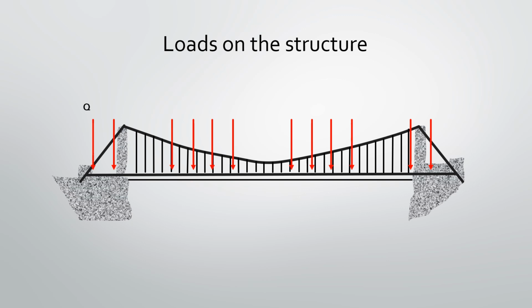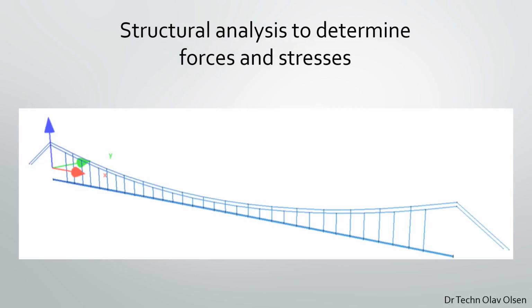Correct modeling of the loads is obviously also important, with the correct load magnitude and placement. The load both at present and in the life extension period should be evaluated, particularly if it is expected to change or increase during the life extension period. When the condition of the structure, including any damage and deterioration found during the inspection, and the loads are established, it is time to do some structural analysis and calculations.